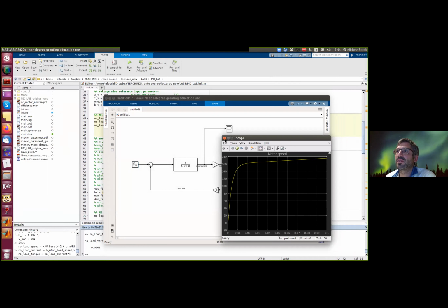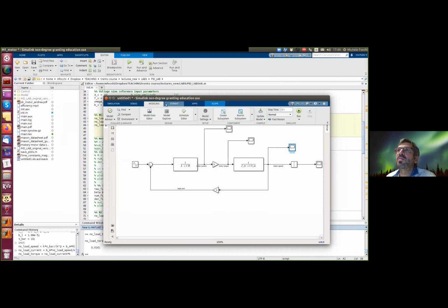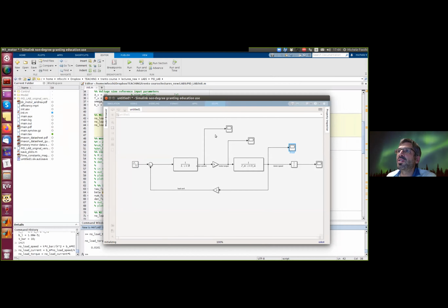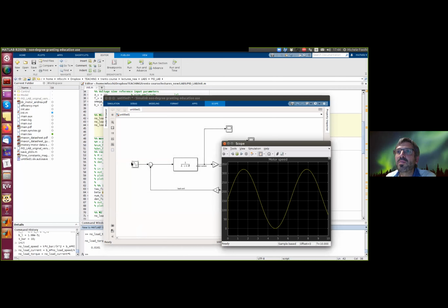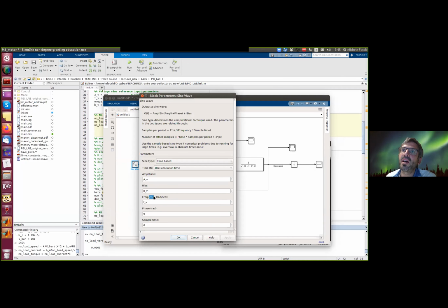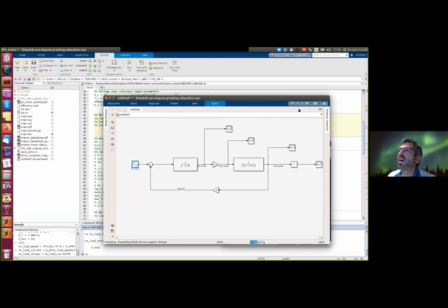that we cannot see anything because the sinusoidal input has a period of 1 second. So to see the sinusoid, we need to increase the simulation time. And now we see sinusoids. Why are the sinusoids so small? Because I made an error. Sorry guys, this is not frequency, but pulsation. It wants it in rad per second, so you need to multiply the frequency times 2 pi. This is the wrong name for the parameter, but for historical reasons, this is what we have in MATLAB.